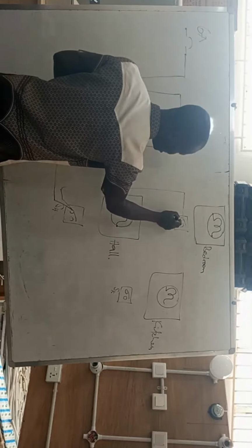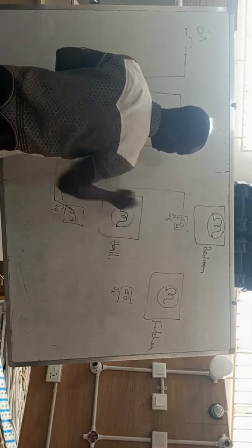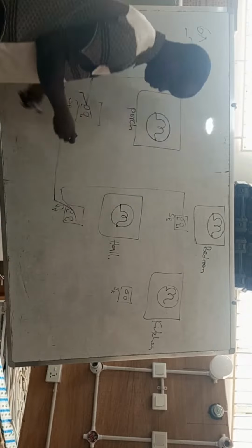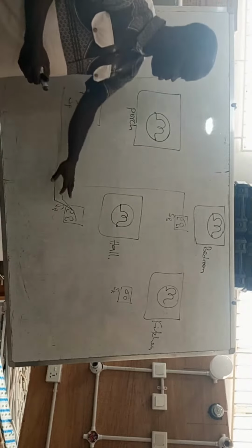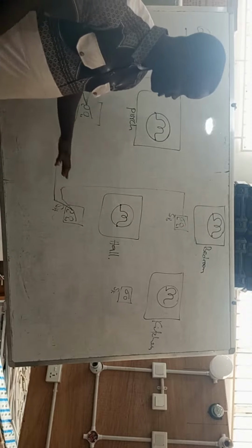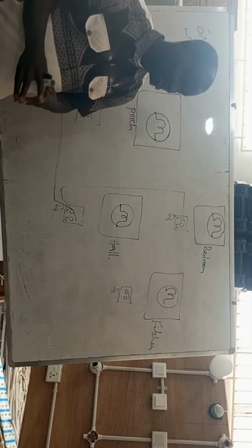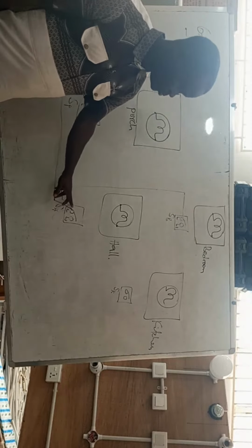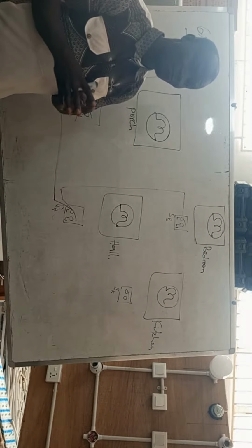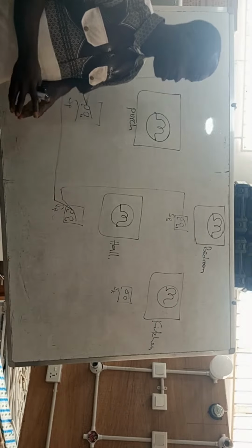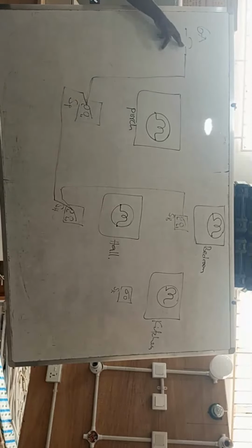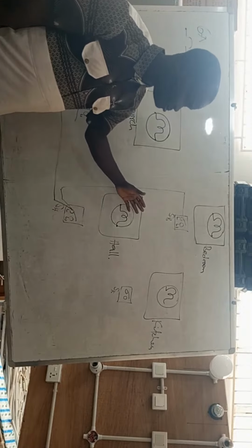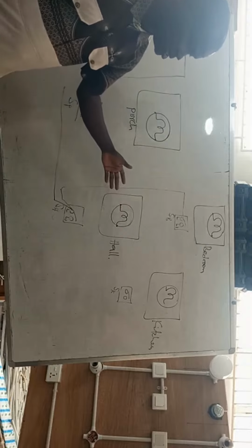So this is L1. Sorry, this is L. This is L1. This is L. This is L1. So if you open your one gang, one-way switch, you will see the terminals marked L and then L1. So L receives the main cable or the feed that comes from the breaker in the consumer unit, and then L1 will now connect to the lamp, as I'll be showing soon.